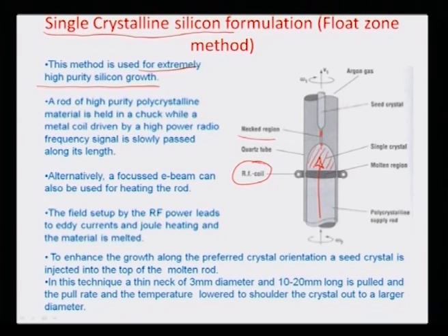Both the rod as well as the feeding rod as well as the wafers are moving at certain omega velocities, and one good advantage here is the uniform heating. So there are very less thermal stresses, and as such no thermal stress related dislocations, which is otherwise the case in Czochralski's method, where there is a huge thermal gradient available because it is essentially a contact mode heating.